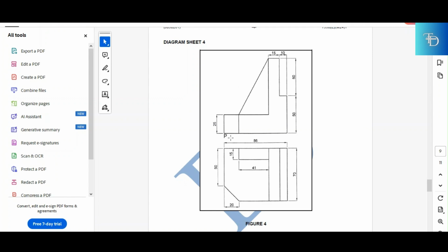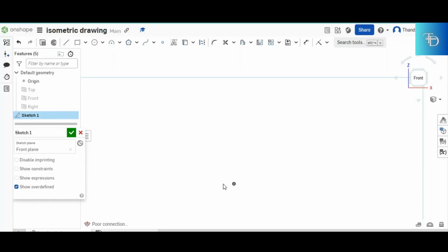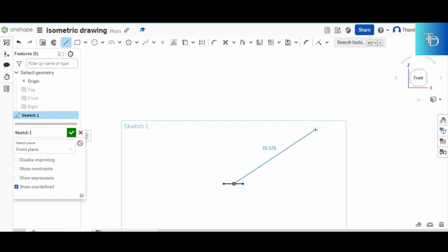And there is our point P, and there was an instruction saying our point P must be the lowest point of the drawing. Alright, then let's go on and create an isometric drawing given these two views. The first thing that you do when you are required to create an isometric drawing is you produce a cube, and the dimensions of that cube, you get them from what? From the given views, from the question. The first thing that you do, you create two lines that are angled at 30 degrees to the horizontal. The first line going this direction and the second line going that direction.